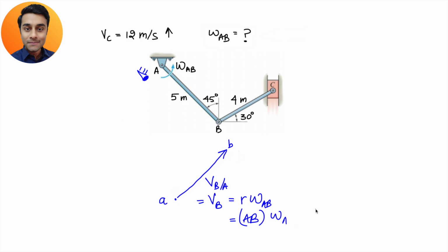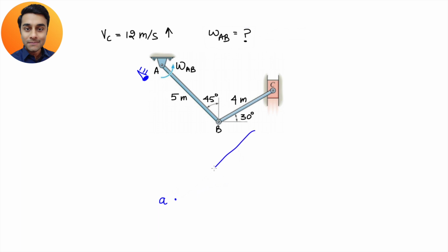In this case also, omega AB is not known to you. How can you say that this vector will be this much in length, right? You cannot be unreasonable. That is why it is not a good idea to start with unknown vectors, those vectors about which you know nothing. It is not a good idea to start with them. You can start with them. You can draw a line like this and say that along this direction the velocity of B will be there. No problem at all. But try to start from those data, from those things which are known to you.